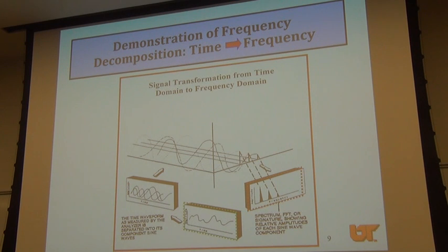Remember now, when you take data from any signal, all those data are digital data. Right? You have only discrete points of data. They're sampled at certain frequency. That's what you get. So what you have to do is process this discrete data or analyze the data either in the time domain or frequency domain, doesn't matter, so that you can get the information in the signal very fast. If I'm doing an experiment and I want to know what the frequency components are, I don't want to wait 2 days or not even 2 hours. I want to get it right now.